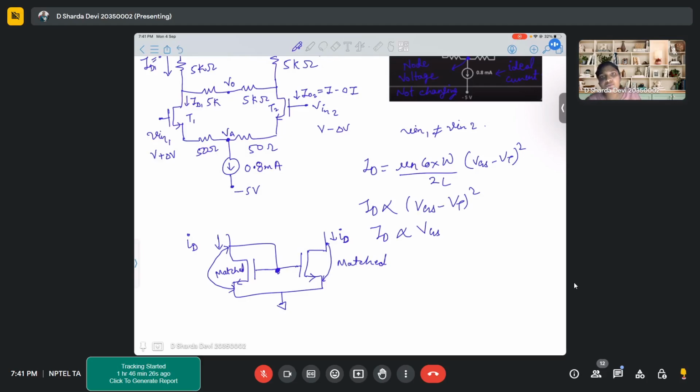So when we say that both the transistors are matched and they are carrying exactly the same current, practically speaking, when will you have exactly the same currents flowing through two transistors? Same voltages and same parameters. And when we say voltages, ideally we should only consider VGS. But in a practical scenario, your channel... VGS as well as VDS should be equal to have equal currents.